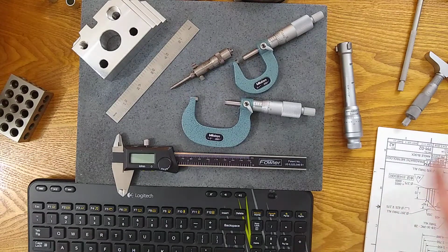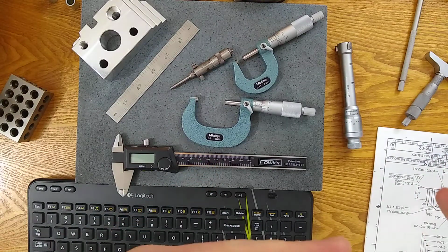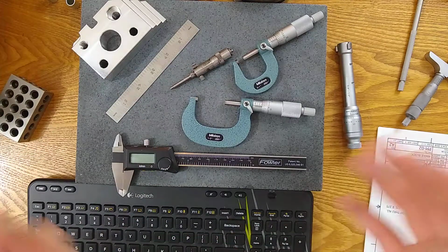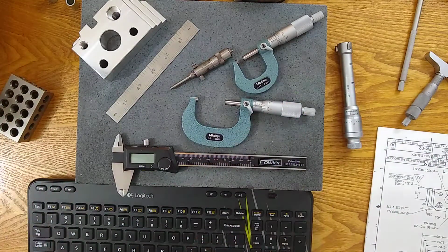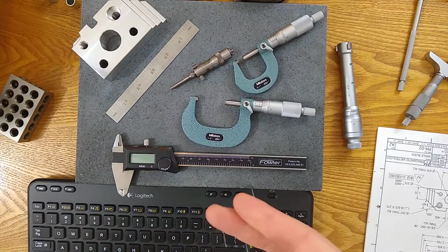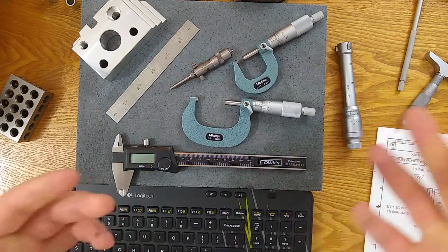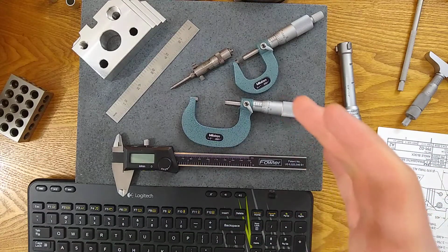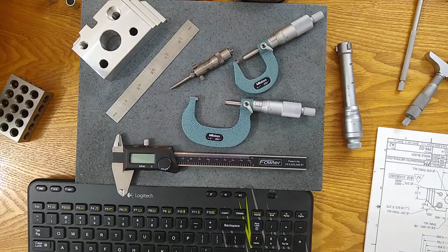If inspection's not involved in the design process, production process, we can be overlooked in our capabilities. So they may give us a part that has challenging features that could have been easier to inspect with modifications to design or production. But because of the way it was designed, because of the way it was produced, it makes it challenging for inspection. And you just say, well, it's designed this way, it's made this way, you just got to inspect it the way it is. And so that comes down to gauge selection and fixture setup and all the questions I outlined before.